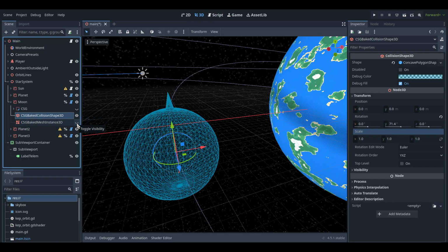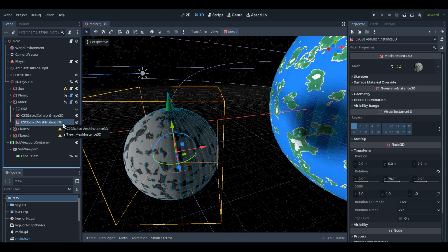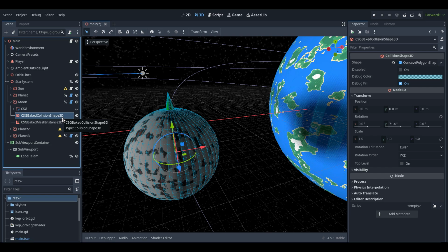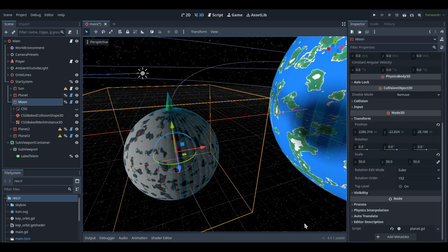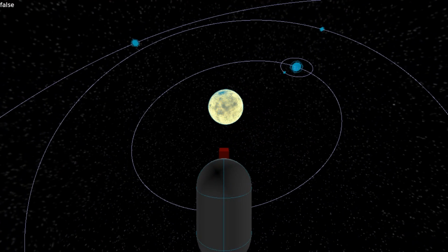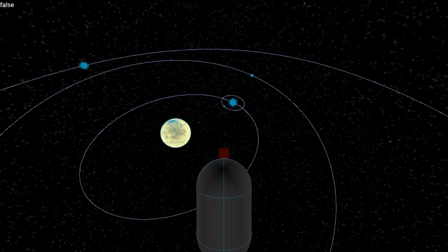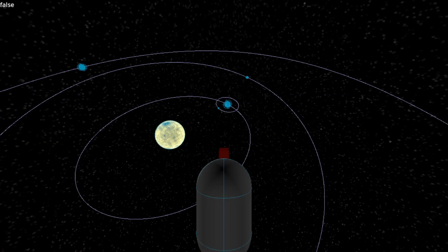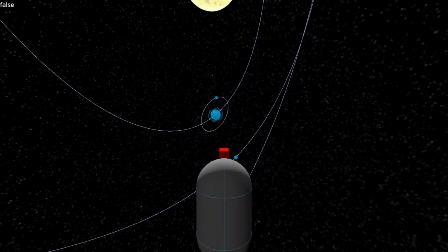Simple. This gives us a much cleaner foundation moving forward, and is much more efficient during runtime, especially once we start adding more complicated terrain features and structures onto the planets later in the series. And importantly, the planets now feel less like temporary editor experiments and more like actual 3D nodes. Later, we can improve this workflow further, even try importing meshes from other applications. But for now, this will let us turn the CSG shapes into meshes and colliders, and even repeat the process again when we want to make changes to the original shapes.